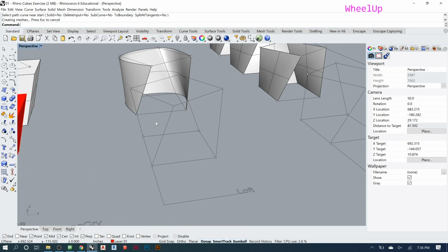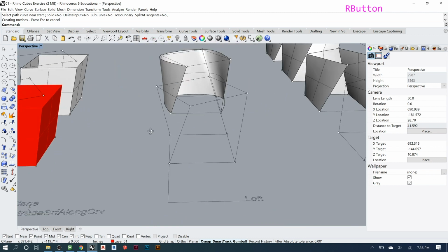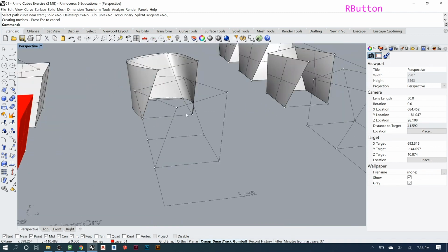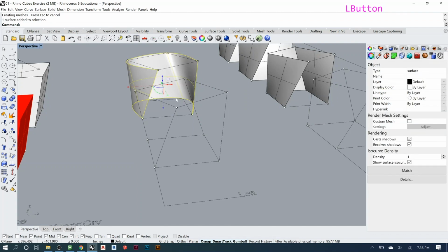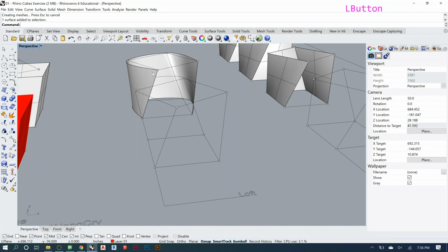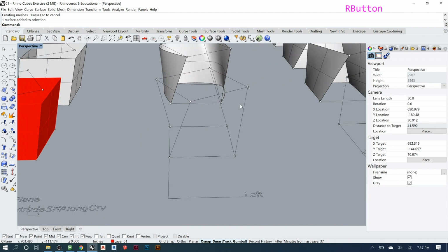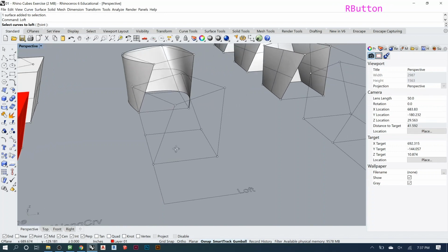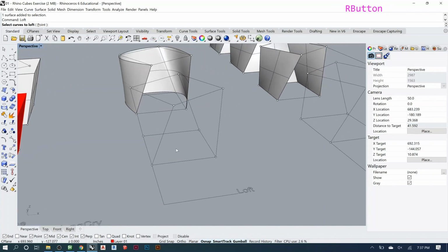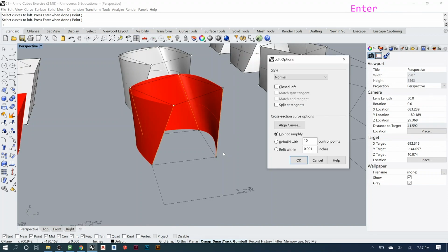So here, you could say, okay, well if I can loft, can't we just grab the loft and loop it all the way around and then get that shape that we've been doing? So if you look here, that's what's going to end up happening. But we can use loft to give us that exact shape we've been making. It just depends how you do it. So by default, the loft is only going to do this. So if I type in loft, and remember what I said, it matters what order you click and also on what side of the objects you click. Because if I want this to look right, I'm going to click them in the right order and hit enter, and see now it's done that.